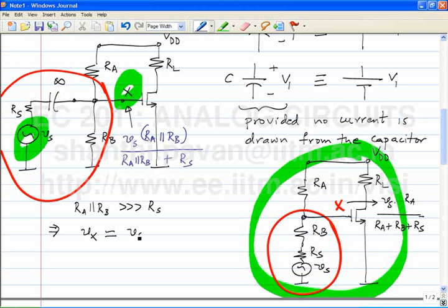Okay. Now can somebody make a comment, similar comment for the one here? The gain will always be less than 1. You understand? Okay. And as I said, there is a practical difficulty of DC current flowing through the source, so it's not quite as preferable as the one on top.